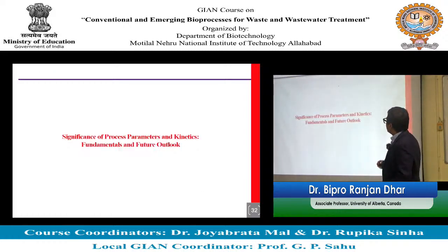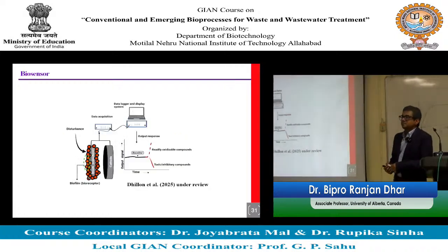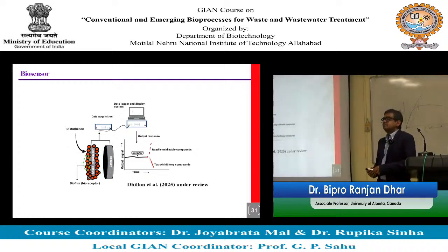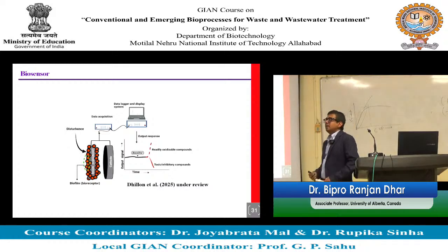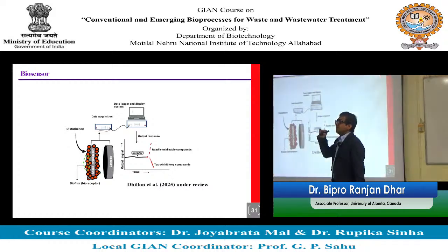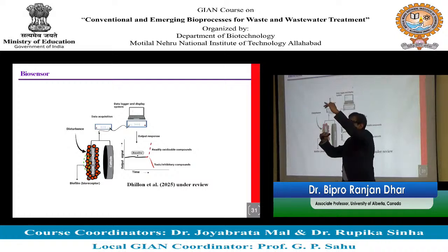Before I jump into process parameters and kinetics, any questions? Yes. Sir, what will be the maintenance of the biofilm? The number of microbes can be increased or decreased in such conditions. If you maintain them with the same concentration of electron donor, it should not change, because it's going to be more like the stationary phase of the microbial growth curve. Growth and decay are going to be about the same, so it should be stable.